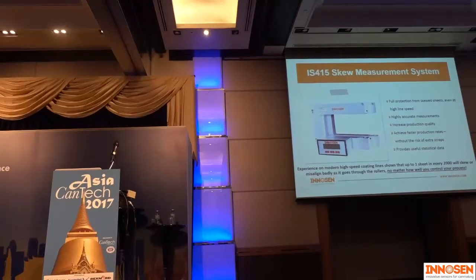The term skew might not be clear for everyone. What it is, when the sheets go into the lacquering line, you want them to be parallel with the side of the lacquering line, perpendicular to the lacquering roll. And if they turn, the margins later are not going to be in the right place. So the turning of the sheet is called the skew. So what this one does is for every single sheet, it measures the skew. And it gives you a numeric value on the display.